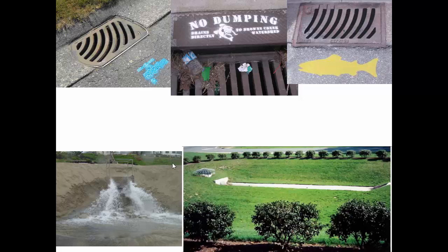But also by having a pond like this, where it's grass lined, it's going to encourage a little bit of passive treatment. So it's vegetative filtration, so that the sand that gets washed off of the road, or salts like I've mentioned before, or maybe oily grit, there is a little bit of reducing the harmful pollutant load before the runoff gets to the stream.